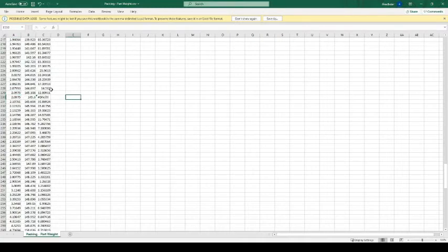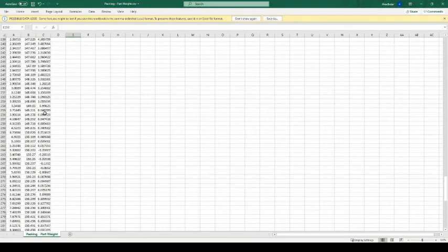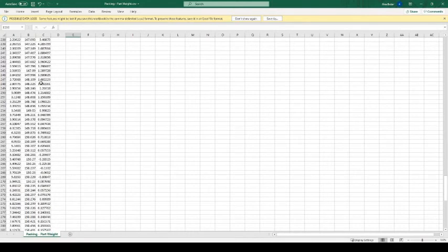That's okay. But we want to figure out where the value goes to very small. You can see that it transitions very quickly from a 0.6 here to a 0.05. That's a tenfold difference, or more than a tenfold difference. And that is pretty much where I would say our packing time should end.